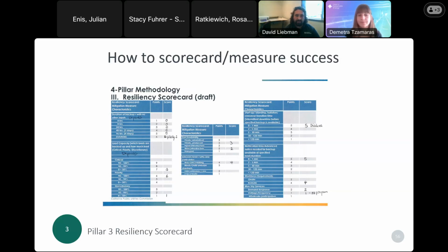For startup and islanding, we scored in less than a minute. As part of the technical challenges of our grant, we've been able to showcase what we call blinkless transitioning. We are able to island away from the grid in under 2 cycles, which means that actually no computers turn off. And so we are able to achieve a blinkless capability.